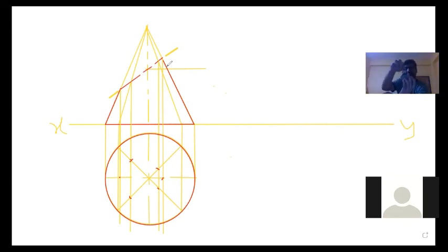Clear? Now if we rotate it onto the slant height, what will you get? You can get this projected point. But if you see from the front, you do not get both points. So from the top view, how can you get it? What we'll do is project the point, sorry, in the front view, we project the point like this.